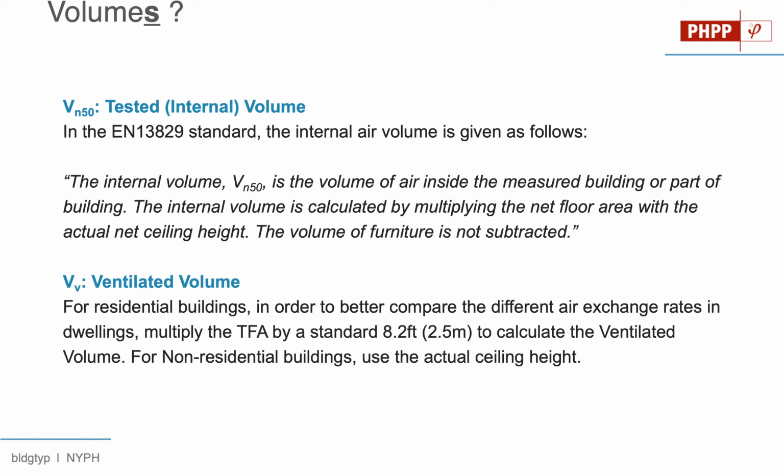Now we have another reference volume, though, which is the ventilated volume. This can be thought of maybe in ASHRAE terms. I think they refer to a similar concept as the breathable air zone. This is the air down where people are. So you might have a 30-foot high space, but when it comes to providing fresh air ventilation for people's comfort and health, we're mostly only concerned with the air down where human beings are. So we're going to use these different reference volumes in different places when it comes to the calculation and evaluation and design of our buildings.